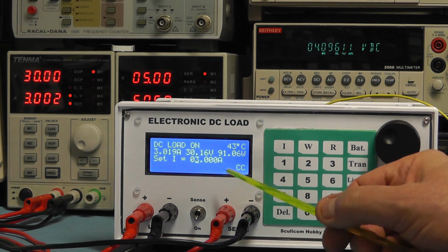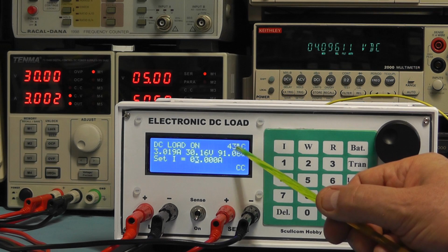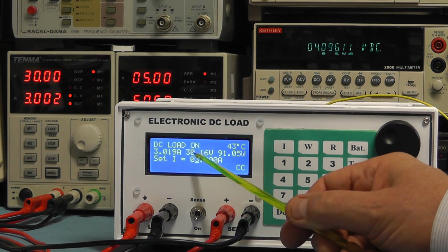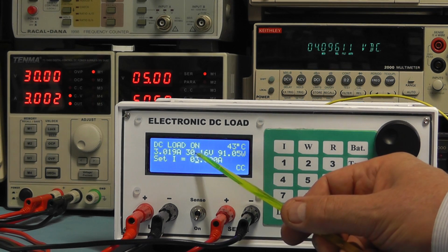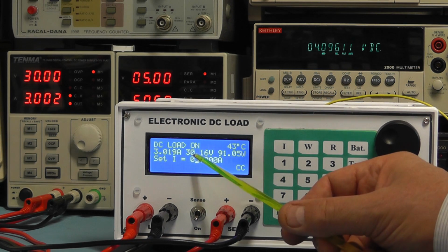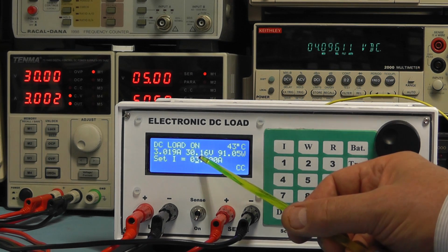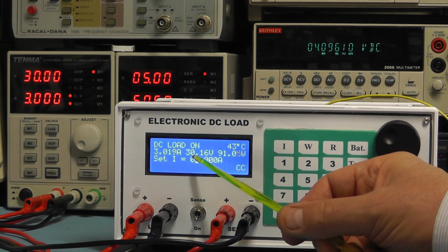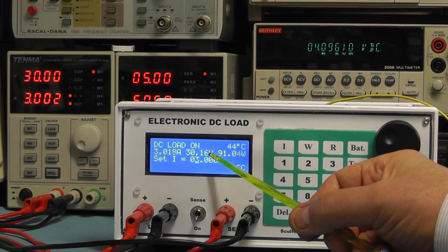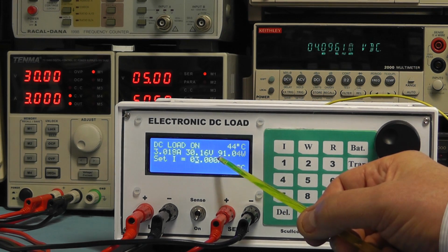Now I've got this set in software, so when it reaches 40 degrees C the fans turn on. And one of the issues we had previously, when the fans came on, we had a slight fluctuation in the voltage reading. You can see now that's rock steady, so we're not getting that problem that we had previously. And that's because we improved the grounding with those wire straps that we put on the underside of the PCB. So that seems to be running quite well now at 3 amps.